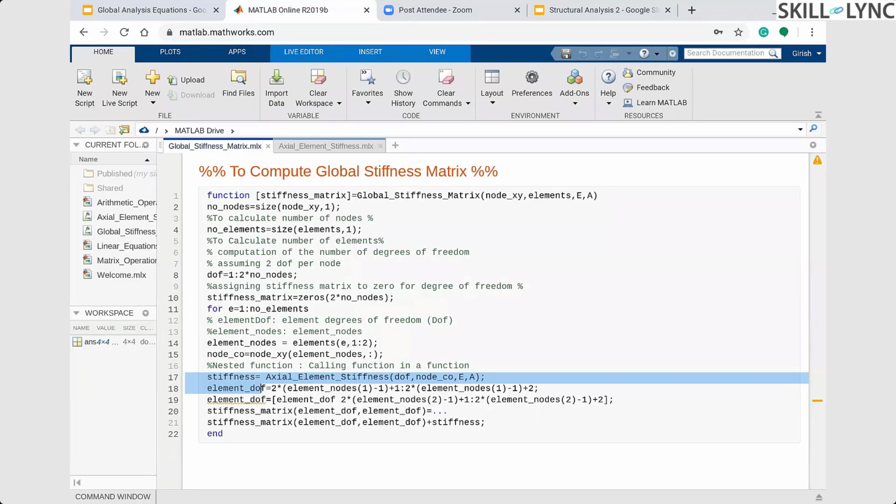So when we take the element vector, which gives the node information, I will explain it to you with an example once I have explained the script. The element vector has the node connecting information. So it's going to be 1, 2. Element 1 is between nodes 1 and 2. Element 2 is between nodes 2 and 3. Element 3 is between nodes 3 and 1. This is what your element vector is going to be.